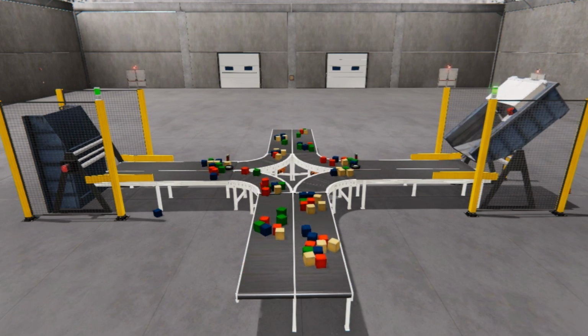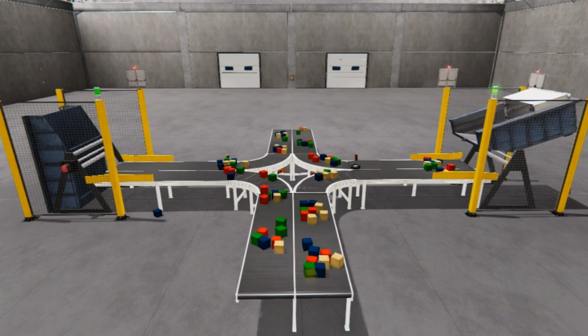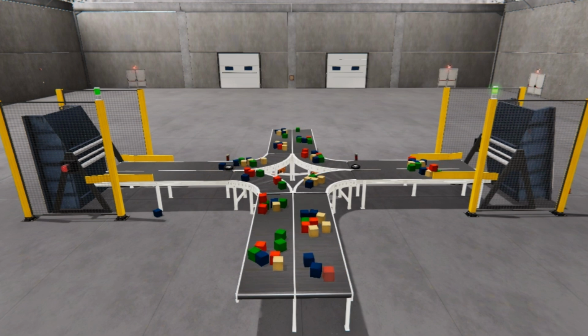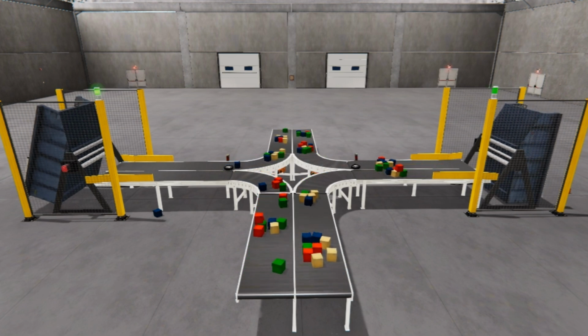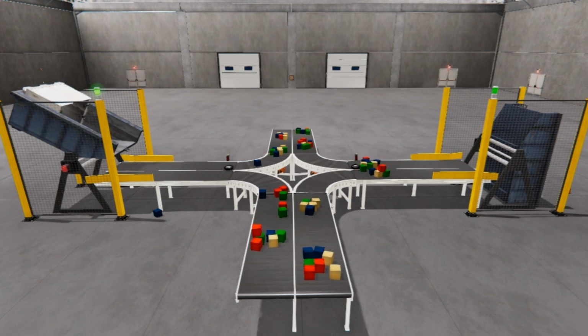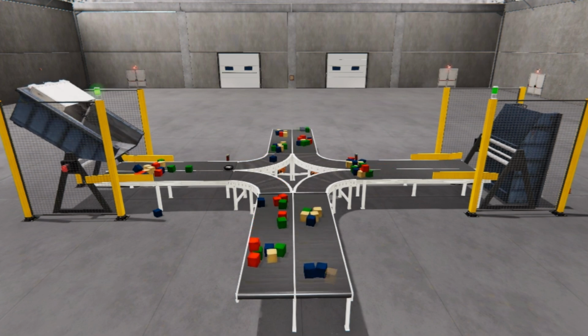When the system is running, all of the conveyors will be turned on. We have 2 box dumpers. These will alternate with each other so that they are never on simultaneously. An internal bit will be used to alternate between the box dumpers.